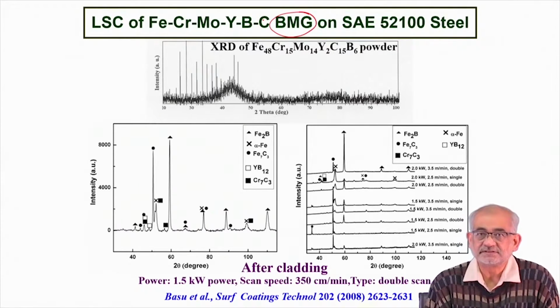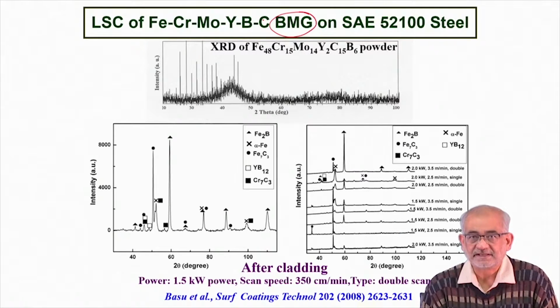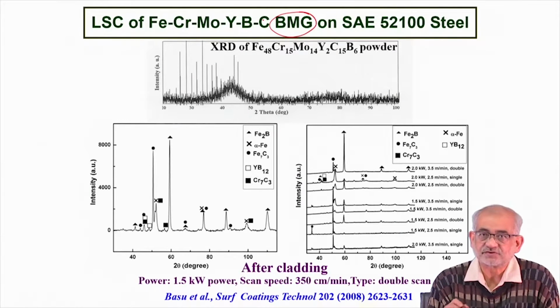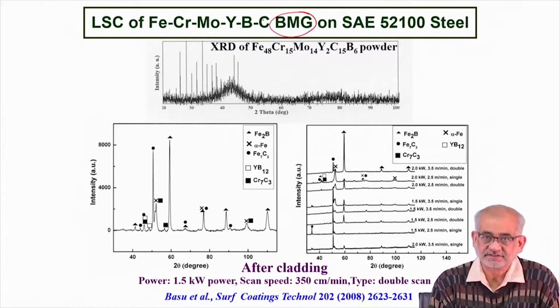But under certain non-equilibrium processing conditions like rapid solidification or high energy milling or high angular axial pressing and so on, we can actually destroy the usual or equilibrium structure, the crystallinity, and then retain a liquid-like structure which we call amorphous, and a subset of that could be a glassy material.